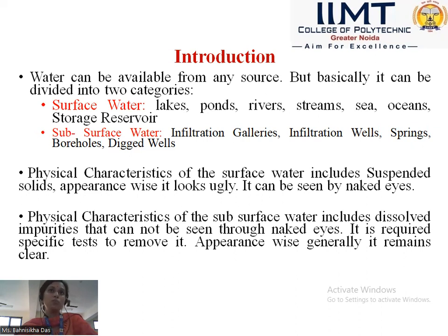The only solid which may be present in the subsurface source or groundwater source is in the form of dissolved solids. So appearance wise, it looks very pleasant in comparison to the surface water sources. However, it may also need to be treated depending upon the dissolved minerals or dissolved gases present in the underground sources.